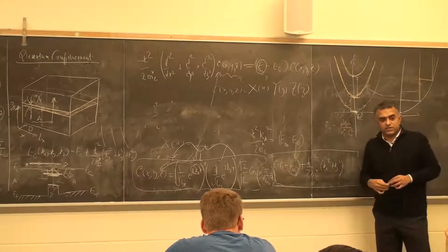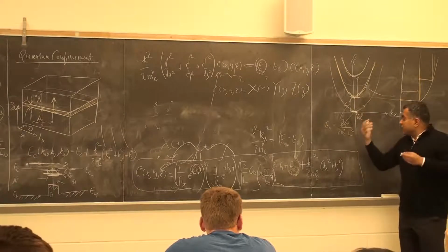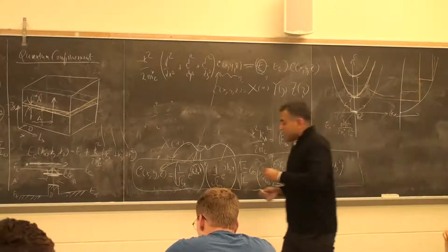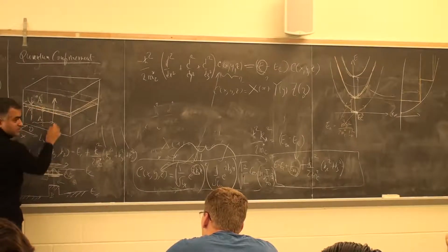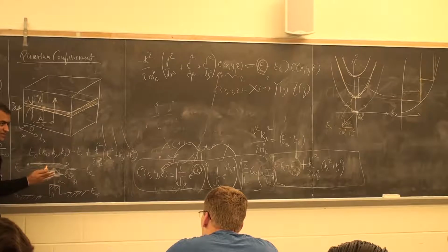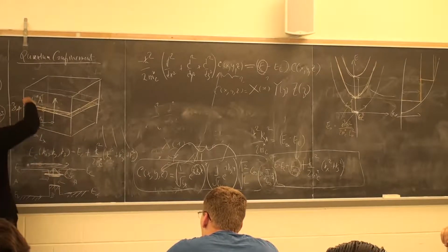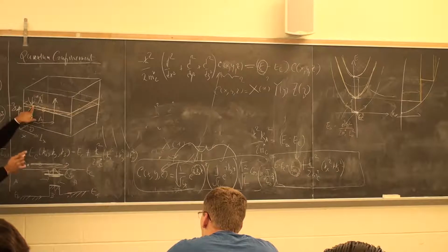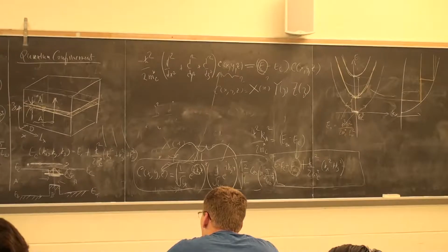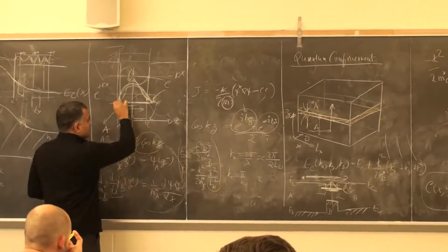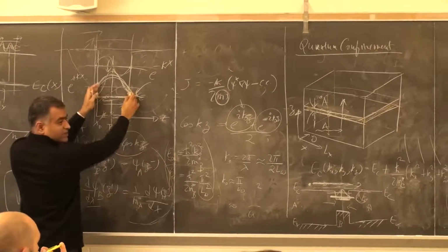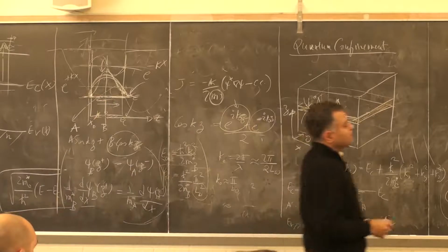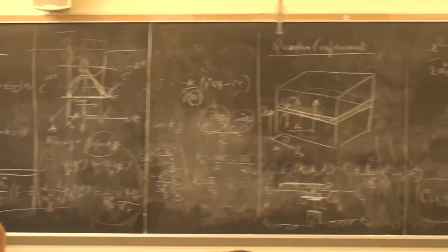For this heterostructure now, this is a good example. My electron is free to move in the x and y plane, right? But let's say it's not moving. It's completely at rest. In a 3D crystal, its energy would be 0, meaning it would be sitting at the band edge. But here it can't, because that energy is not allowed anymore. The minimum energy allowed is here now. Because it's quantum confined, its wave function cannot match that. Therefore, this energy for the quantum well is not allowed anymore.